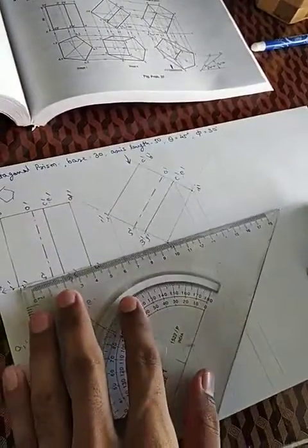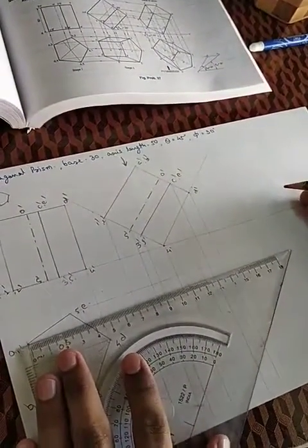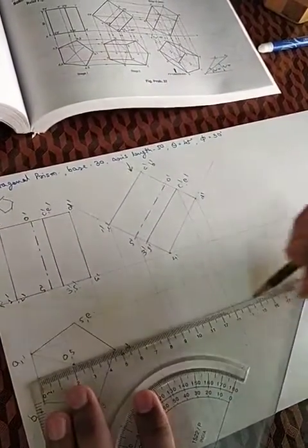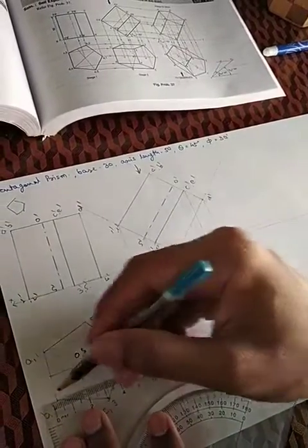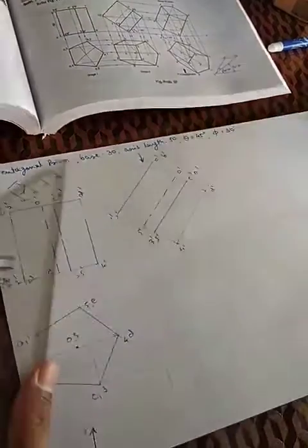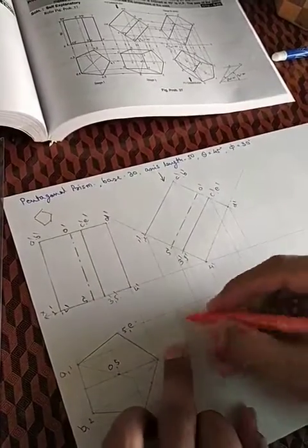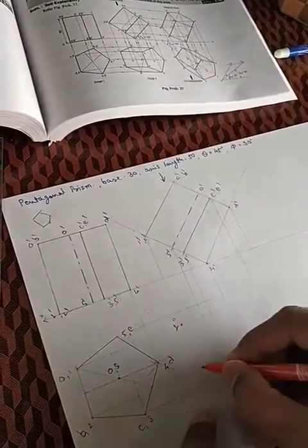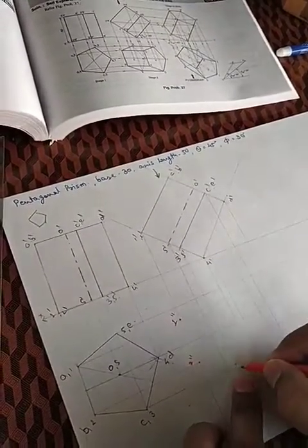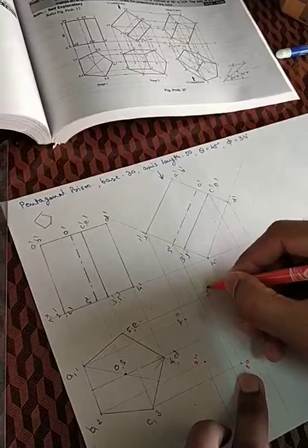And from this figure, draw projections in right side direction from each and every point. Now you can find the intersection of each and every point. Here this is line of 1 dash 2 dash, so where is 1? So this will give me 1 double dash, this will be 2 double dash. Similarly you can find this is line of 3 and 5, so this will be 3 double dash, this will be 4 double dash, and this will be 5 double dash.